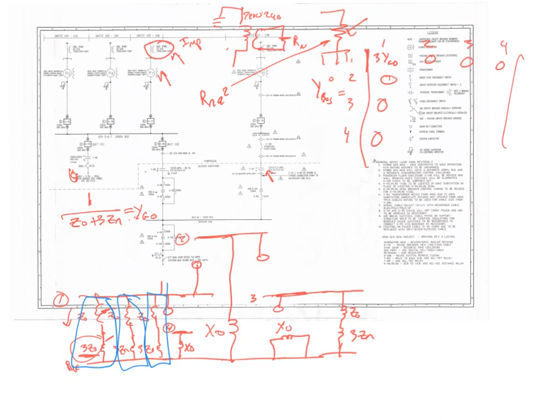So where do we get that? Is it in the data sheet for the generators? For this case, you just put 3Zn. If I wanted you to actually calculate fault currents, well, that's okay. When we build the Y bus, it's 3 times the impedance because there are 3 generators. It's 3 generators, but the 3Zn is there because why?